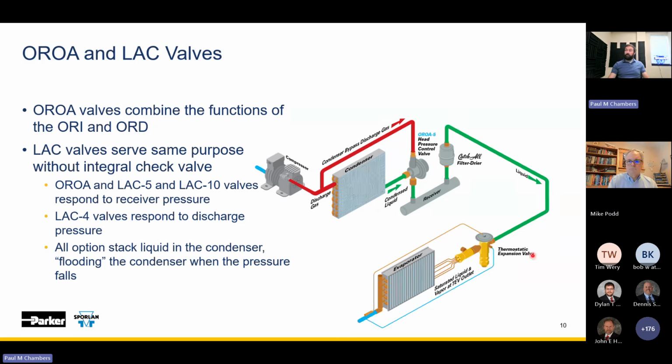Another good point, since you brought that up. Here we say expansion, we say thermostatic expansion valve because we're specific, right? You could say expansion device is another. If I'm drawing a generic refrigeration system, I might write that. But another one I've also seen and written myself is pressure drop device, because that's really the point of the expansion: the pressure drop.